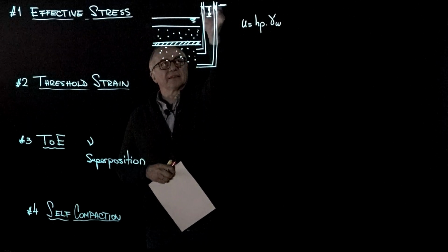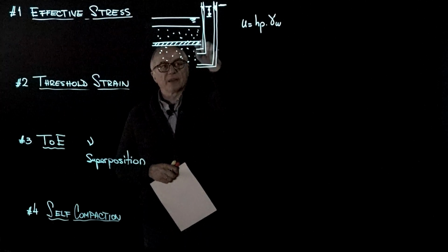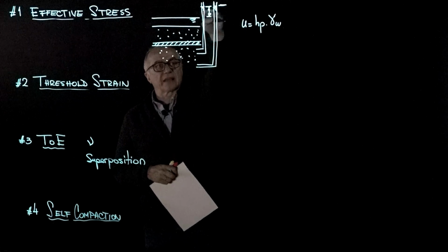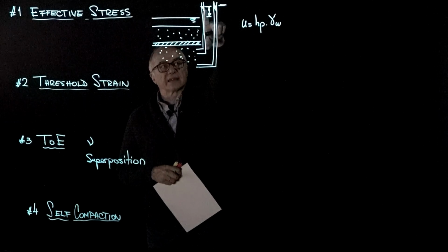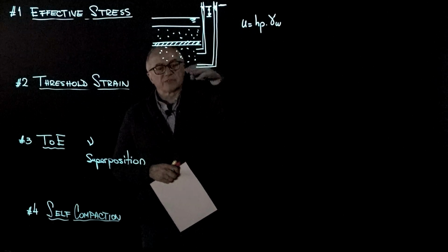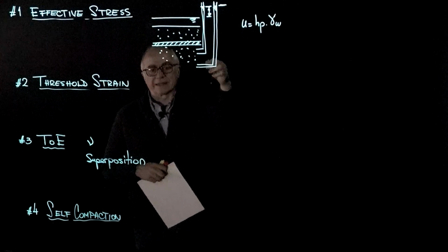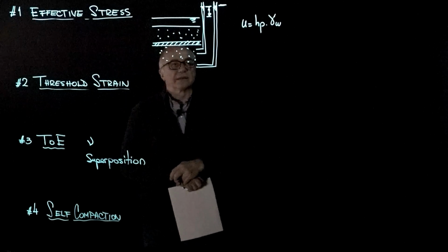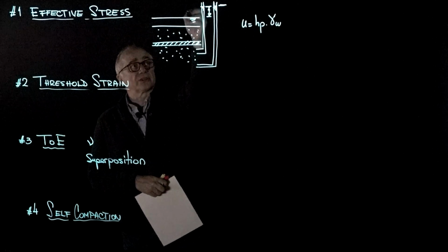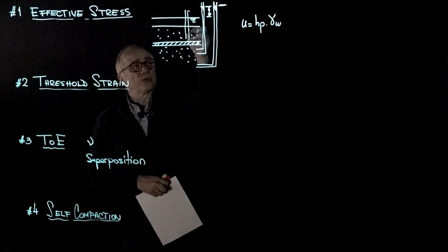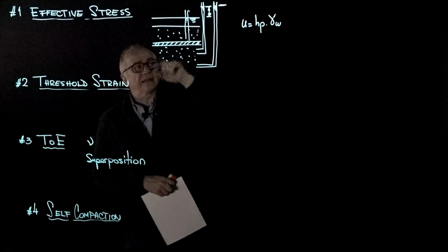So once again, the lower part is under hydrostatic conditions. So wherever you place a piezometer, it will rise to the same elevation. So then the question is, what is the height inside the piezometer, which will be some relationship with the elevation with respect to your first piezometer or a datum that you have established. The second part is that if you place a piezometer from the top, the water is also hydrostatic and it will rise to where the water table is.